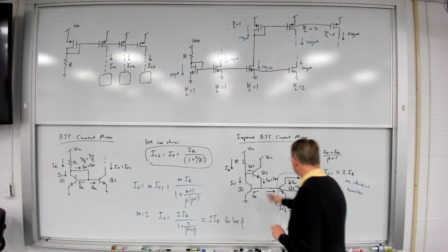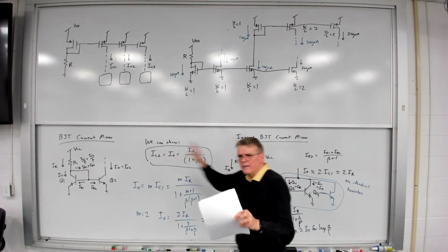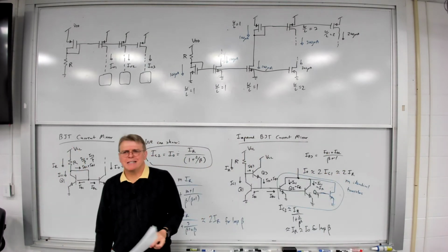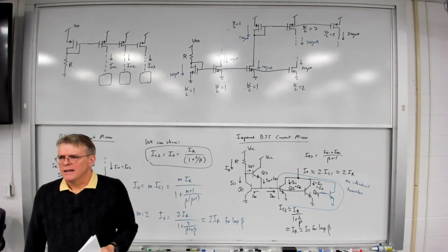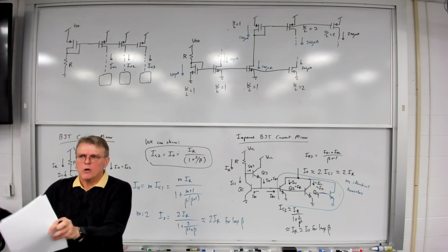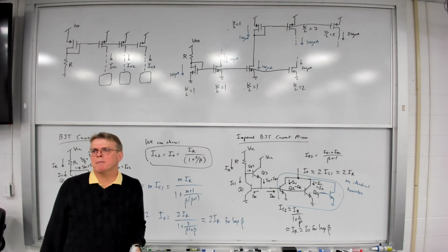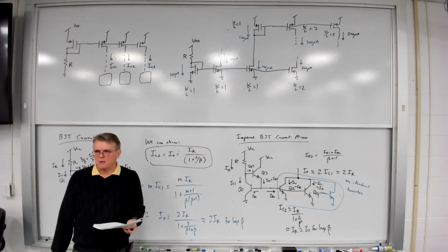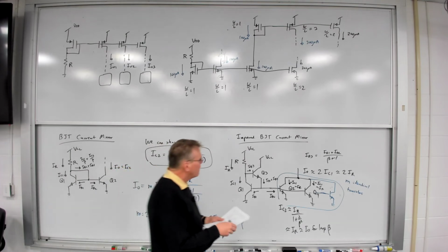So, again, current mirroring, extremely common technique. You see it everywhere. And you will see this idea of connecting these devices in parallel to sum currents together. Extremely popular concept, very, very commonly used in IC design.